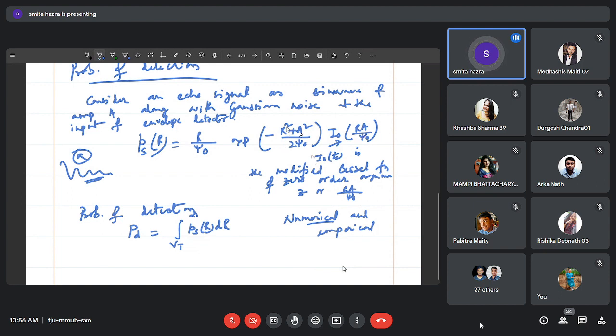So when we do this for A, what does it actually mean? Because inside this Bessel function, there is also rA by psi naught. Okay. So let us first indicate what this A by psi naught actually means. If I write this, that is A by root psi naught. What does this say to us? This A is the signal amplitude, because here we have considered the echo signal of amplitude A. So A is nothing but the signal amplitude, and this psi naught is the RMS noise voltage.